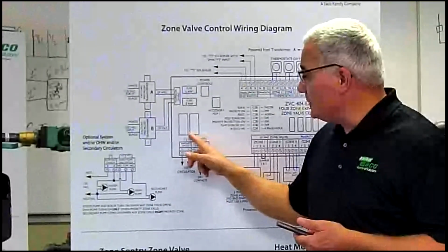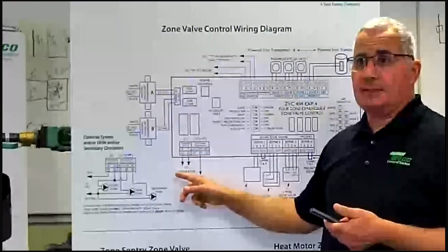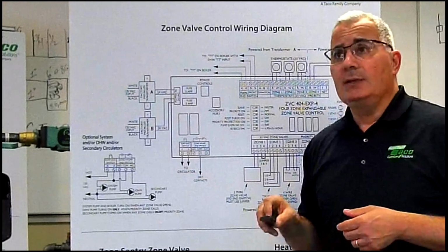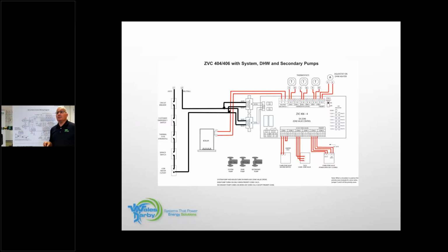But these contacts here, these are called dry contacts. So they're switches, but we have to bring power into them. So on the PowerPoint, you're going to see we're going to bring power into them. All right. Here we go. So power's coming in one side here. Then power is going to come out. We're going to pick up one side of the main pump. We're calling that the system pump. Then you also see that there's a jumper coming across to the common.